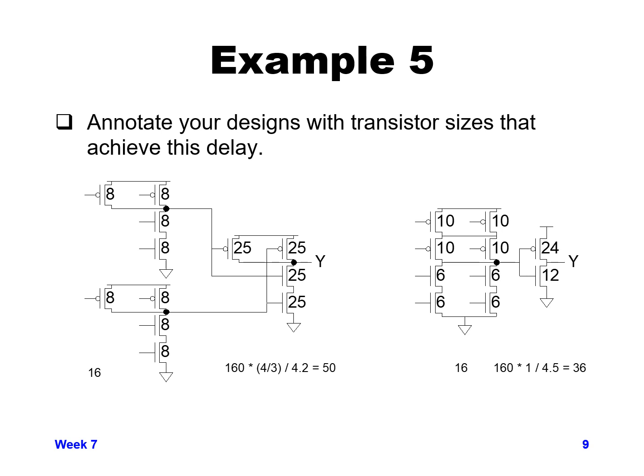So if you were more concerned about the area that you're taking up than you are the absolute delay, you might determine that the solution on the right is smaller and more compact and fits in the area, and you might decide to use that over the one on the left, even though the one on the left might be a little bit faster. So again, these are ways that you can trade off different parameters, speed versus area in this particular case. Depending on what is more important to you, you can decide on the two different designs.